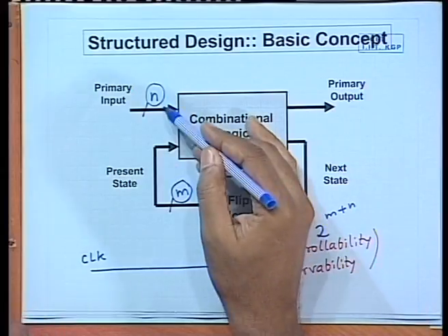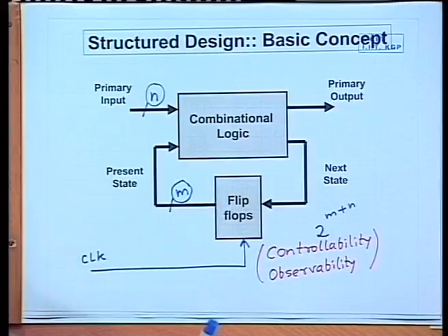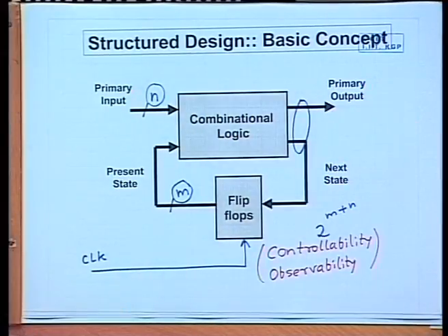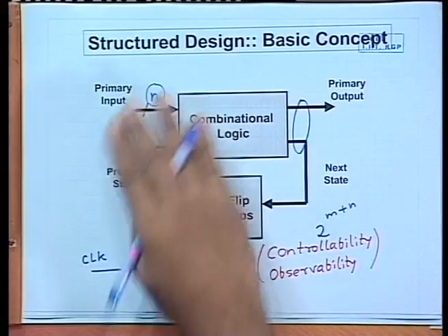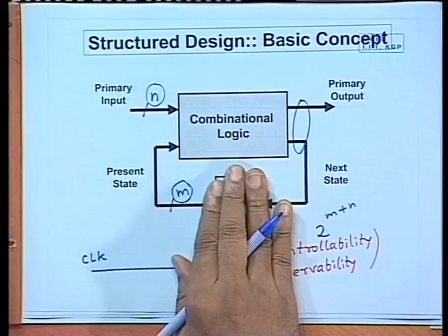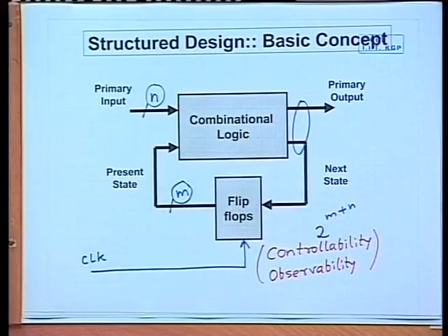So, as if all m plus n inputs are available to me, and similarly all the outputs are also available for observation. We can forget flip flops for the time being, and we can use a combinational test generator which is relatively much less complex for generating the test patterns. This is the basic idea behind the structured design for testability techniques.